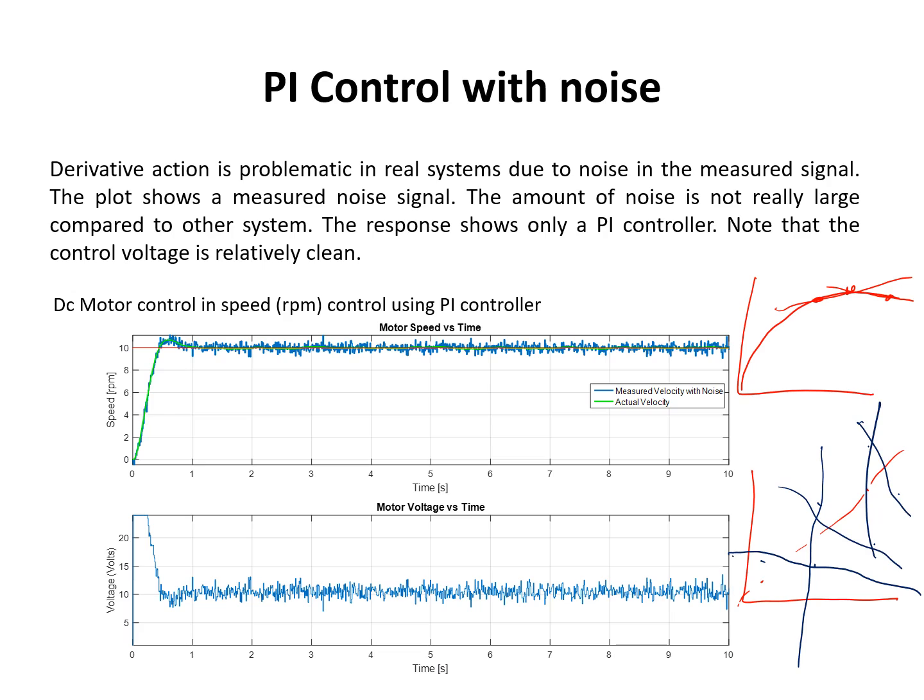Right, so you'll see your derivative error here is negative, and then positive, negative, positive. So it's quite a noisy error in general because we're only using 2 terms to approximate the error term. There are approaches where again you can filter the error, or work out the derivative using more points. That typically smooths it as well.